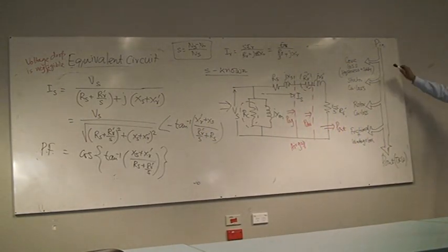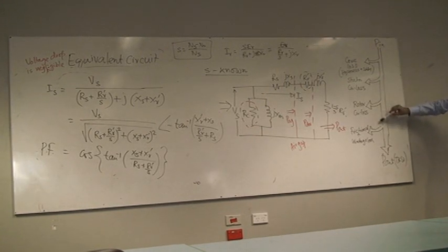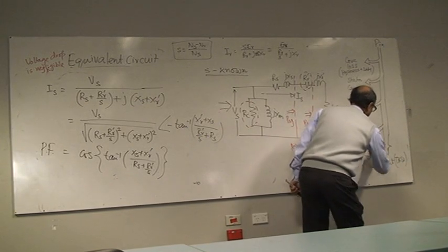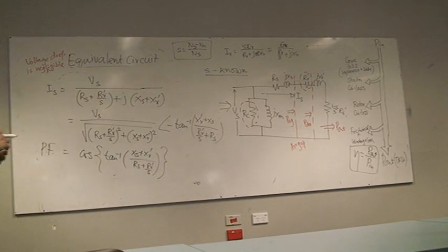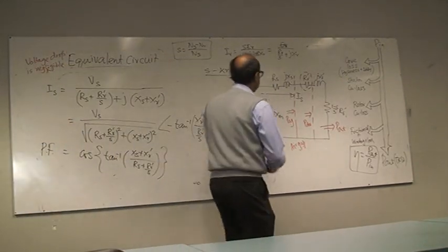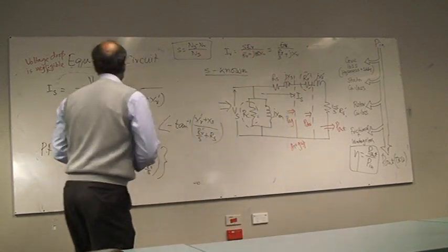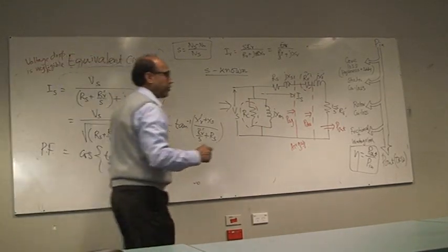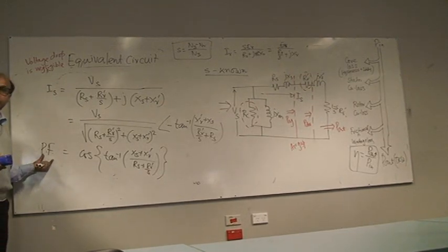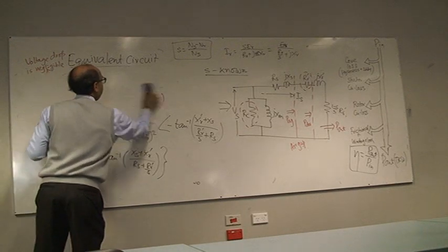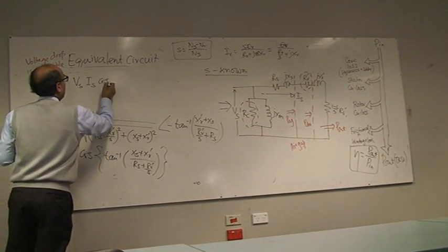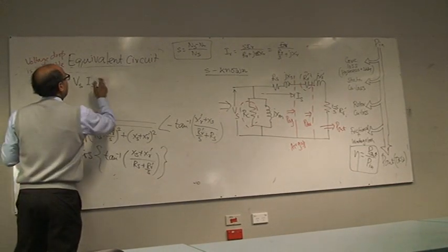So this is the power flow diagram, which gives you a clear idea: we have given the input, the losses go out, and then the remainder is output, and of course we define the efficiency as P out by P in. Now what we want to see is what the air gap power will be. First, what will be my power input in terms of an electrical expression? I can calculate the current, and I have also got the power factor. So the power input is Vs, Is, cos of the angle, the power factor.